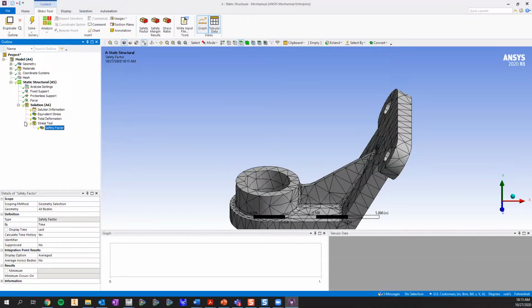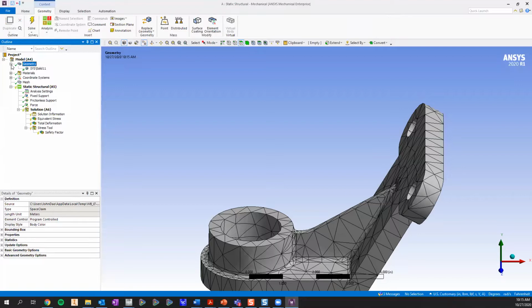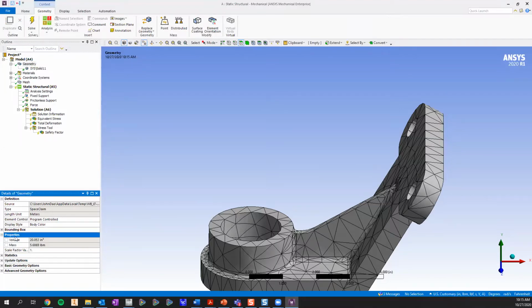Those are going to be features or values that we change. Now I'm going to be setting parameters from the outputs. So it's like cause and effect from your inputs. And I'm going to parameterize the mass. So I'm going to select geometry, and you can see where it says mass here. There's going to be a little box here. That's not a checkbox. That's actually your parameterization box. And when I click here, it's going to parameterize mass.